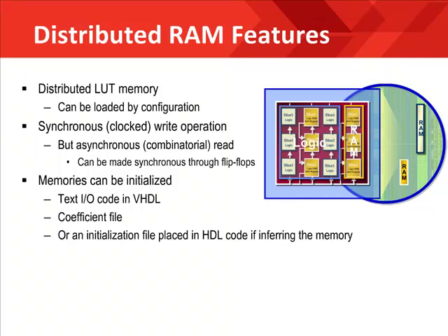The write operation of distributed RAM is synchronous and the read operation is asynchronous. The RAM output can be connected to the flip-flops in the same slice to create a synchronous read. Most customers are creating distributed memory with the core generator utility because it will create the necessary input decoder and output multiplexer logic automatically.